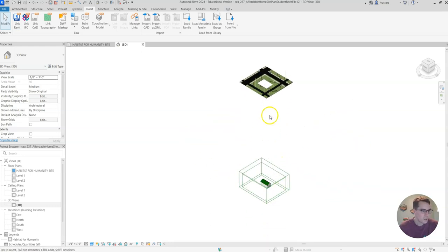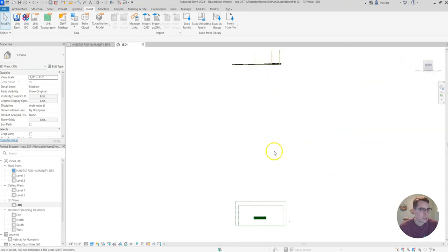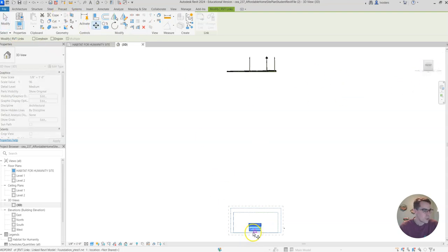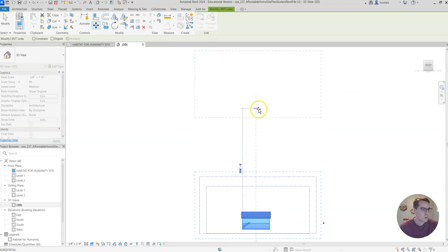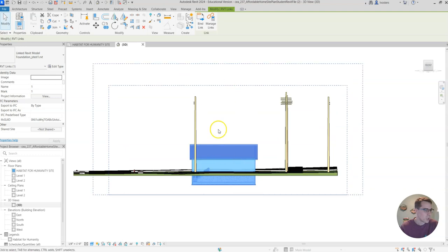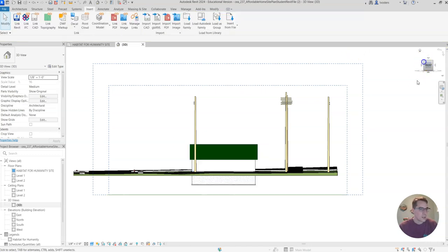And again, since we have an elevation here, you can see that it just placed it way below where I want it. So from here, you'll want to go to an orthographic view and then use the move tool. I would click just anywhere on there and then type in, let's just do 770 feet, hit enter, and it should move it basically straight up to where I want it. All right, so we've got our house placed where we want roughly.